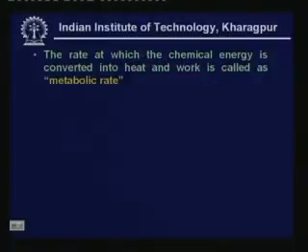In this respect, a human body is like any heat engine. If you remember, we discussed the heat engine, and I mentioned that a heat engine is nothing but a device which takes in some chemical energy in the form of a fuel and converts a part of it into work and a part of it into heat. A human body is also like that. The rate at which the chemical energy is converted into heat and work is called metabolic rate.